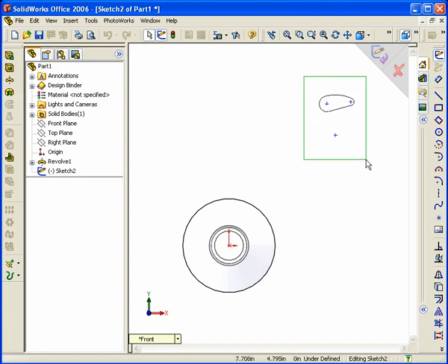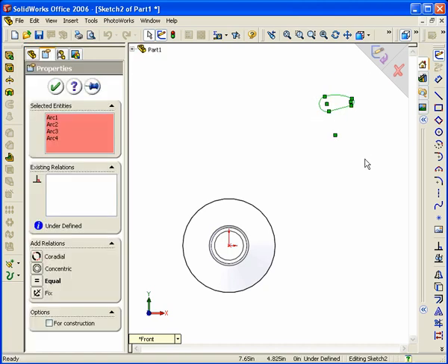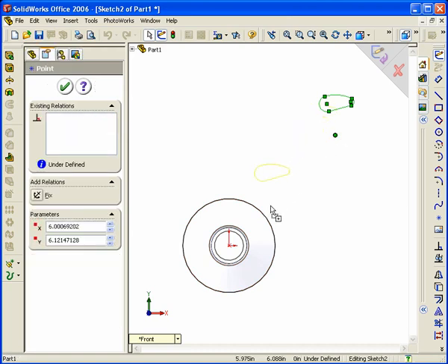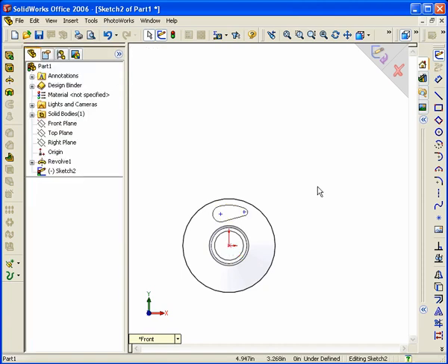I'm going to group select the geometry, and hold Control and drag that center point to the origin. So let's do that now. Grab the Control key and the left mouse button, grab that center point, drag it over and lock it in to the origin. Release the Control key first, and then release the mouse button. And it will copy and paste this for us.